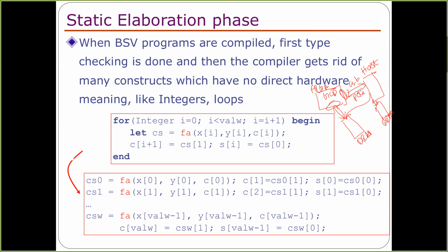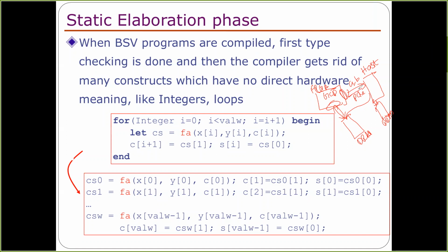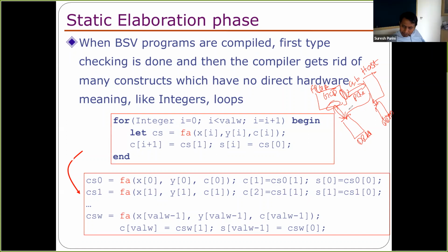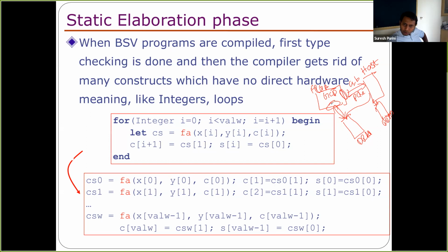Yeah. So basically, let's say we have GCD for different types. Let's say we have made a parameter for GCD, and then in the host you're calling GCD for let's say 1-bit numbers or 2-bit numbers, 3-bit numbers, etc. So they'll be instantiated because they already have a queue for that. So we need to have those different modules. You need to have a 32-bit GCD module, a 64-bit GCD module. There will be separate hardware entities present here, because it cannot dynamically expand from 32 to 64 or 64 to 32. They will be instantiated.